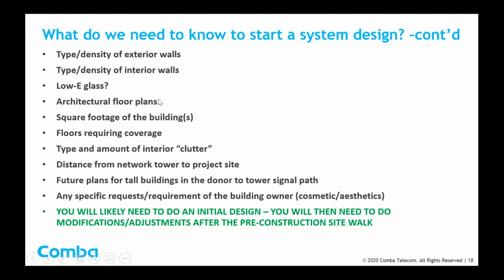It's nice if possible to have architectural floor plans. The more detailed and better the floor plans are, the more the RF designer doing the system is going to love you. What's the square footage of the buildings you're going to be covering? How many floors require coverage? What is the type and amount of interior clutter? Interior clutter is everything inside the building.